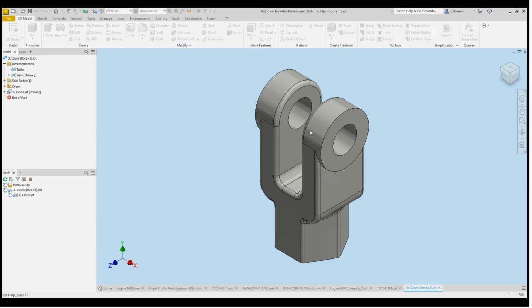The other thing that's nice about this is I can navigate my folders here. The project file is grayed out. So most of us are using Vault today, so we only have a single project file. We have others that are not using Vault. They have many project files. And so you always have to close your files, go to your settings, change your project file, and then open the file. You can now do it right from here as long as there are no files open in Inventor. Again, that rule has not changed. You can't switch project files if files are open. If files are closed, you'll be able to change the project file here.